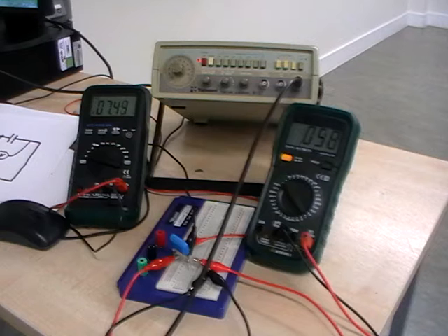Now, we've got coils and we've got capacitors. Something happens with our capacitors when I measure the resistance in DC conditions, and then something different happens when I do the same thing, trying to work out the resistance while feeding an AC signal through the capacitor. And that is called reactance. So for example, if I take a capacitor and measure the resistance in DC conditions, I'll get something like infinite resistance, several megaohms. It's sky high. But then I place it into a circuit and I apply an alternating current.